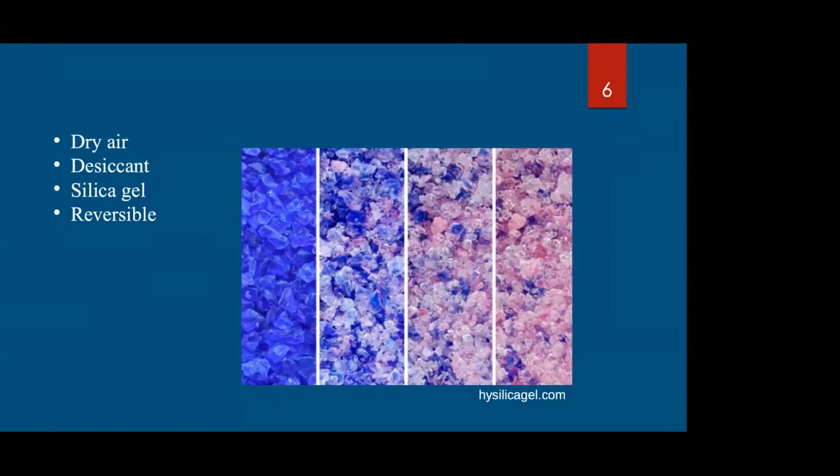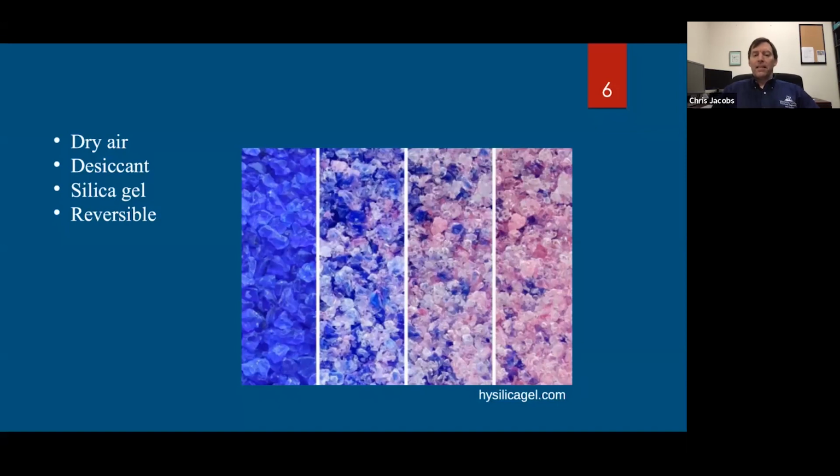Yes, great. Now we have another question. Is there a chance to measure specific gravity of liquefied natural gas in liquid state? Not with this particular equipment. If it's in a liquid state, you probably have to use a liquid gravitometer, because this is comparing a gas. When you're measuring the specific gravity of a gas, you're using dry air as your reference material. I know liquefied natural gas is compressed, but if you're going to compress it, that's going to follow your PVT principles.